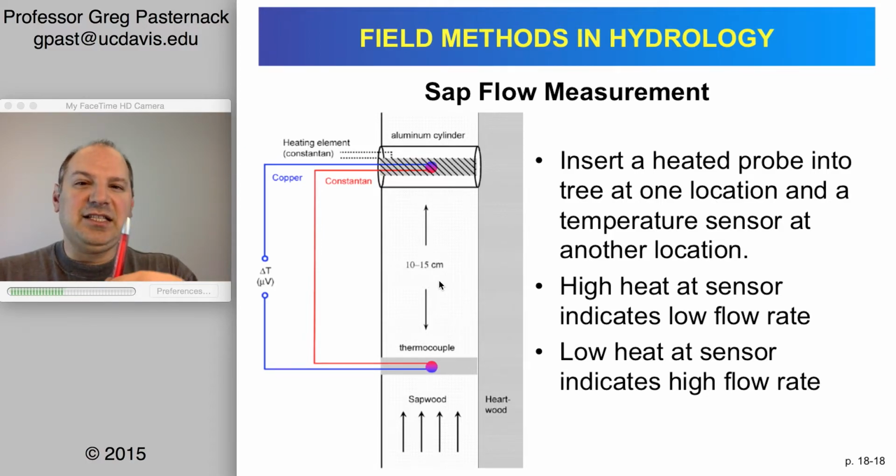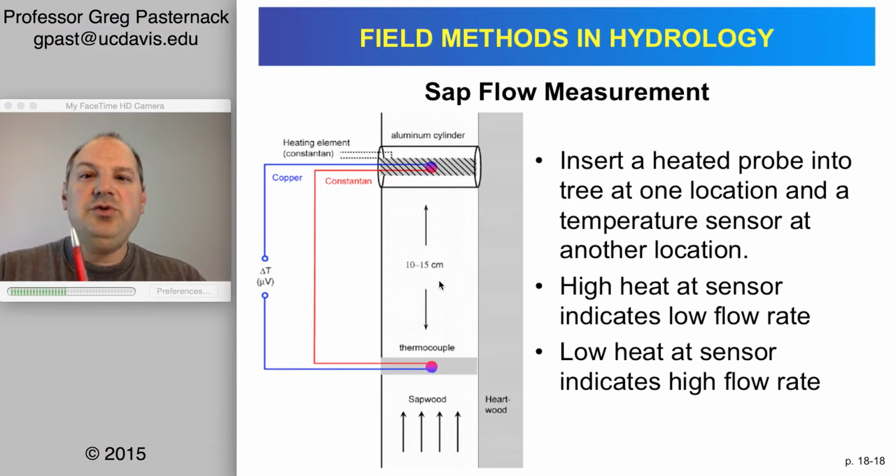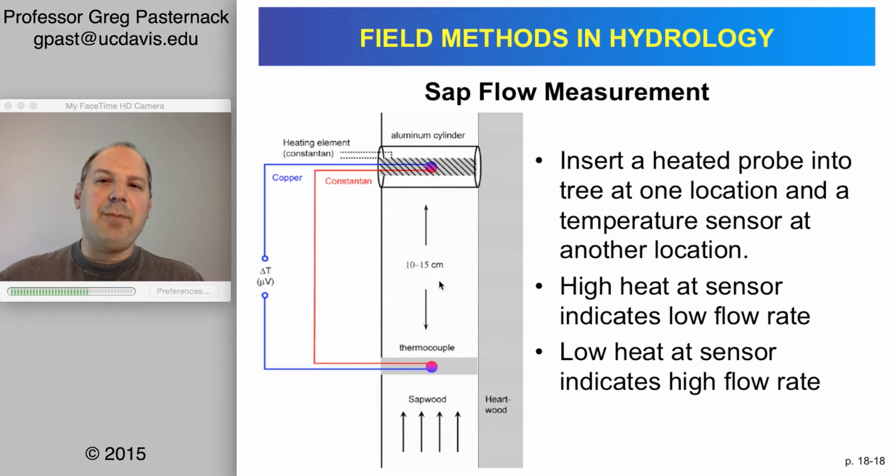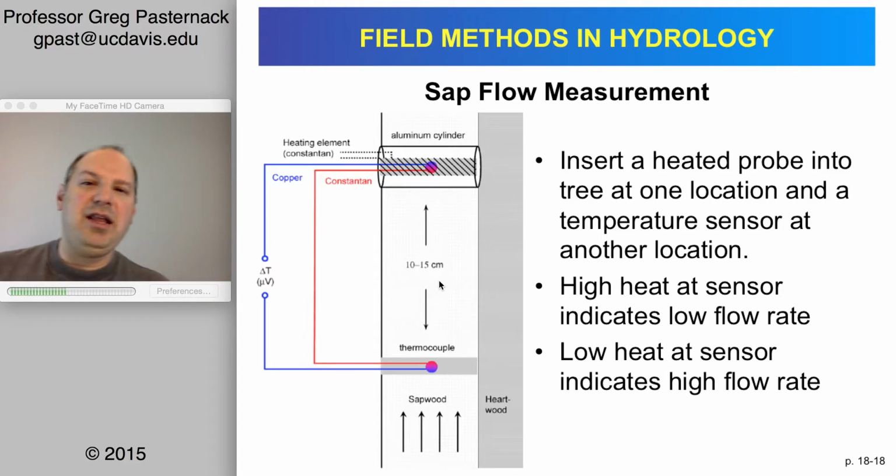The process by which heat moves away from an individual source is a diffusion-based process, again, governed by the gradient, unless you have some sort of turbulent mixing or something else going on. So you have a nice bell curve that's around here. Now what if I take a bell curve and I apply a unidirectional gradient to it?